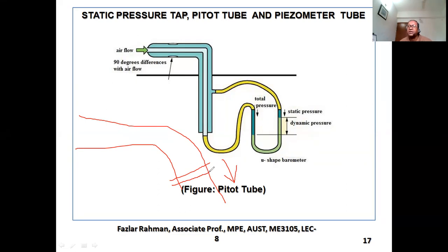At first, you need to know what the stagnation pressure will be, because the fluid is coming with a certain velocity and also has static pressure. Then when it comes over here, it will have the same static pressure plus this much kinetic energy converted into pressure, so the pressure increases. This pressure is the stagnation pressure. If you know the stagnation pressure, at least at the initial stage, you can figure out what size and what kind of material you can choose to design that dam, or to protect the gate, or to protect the water. So that is the application of stagnation pressure.